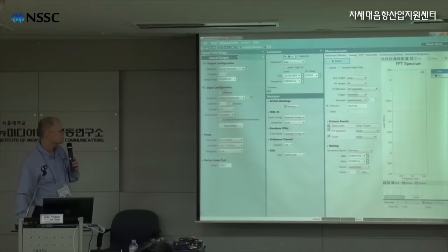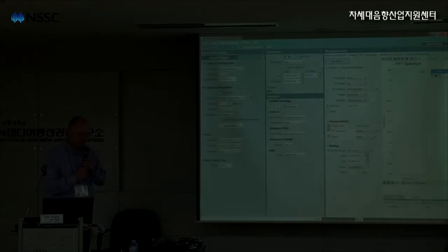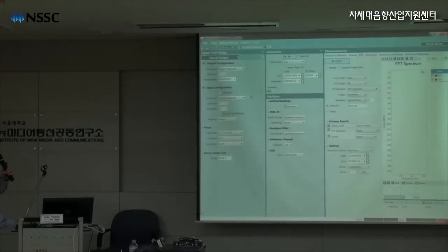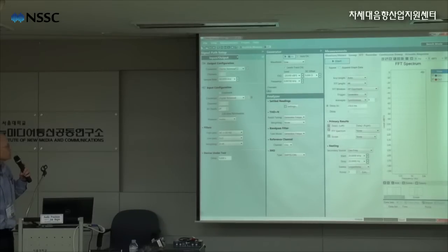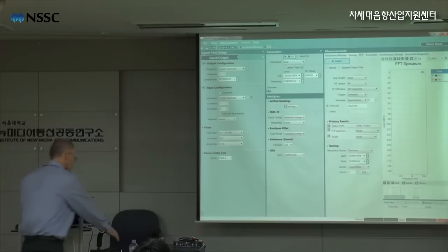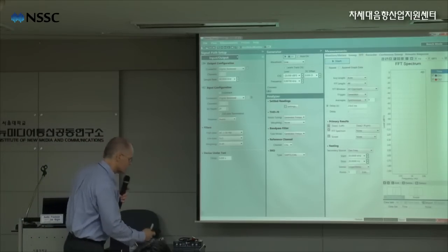And actually, I think what I'll do is connect a cable directly. So I've set the output to digital balanced and the input to digital balanced, but you'll notice I haven't connected a cable yet. And in this green on black indicator down below, it's showing that my output is digital balanced with a sample rate of 48 kilohertz. On the input side, the input is digital balanced, but there's a big red indicator showing that the sample is unlocked. So there's no cable connected, no signal coming in, and the analyzer is telling me that it's unlocked.